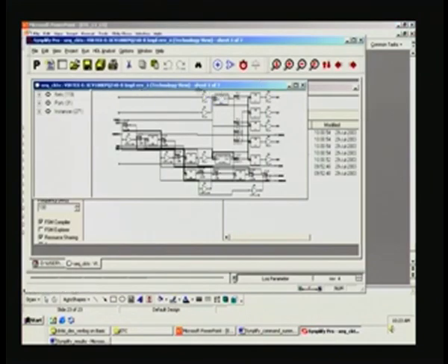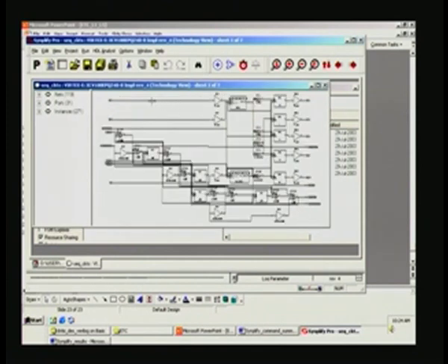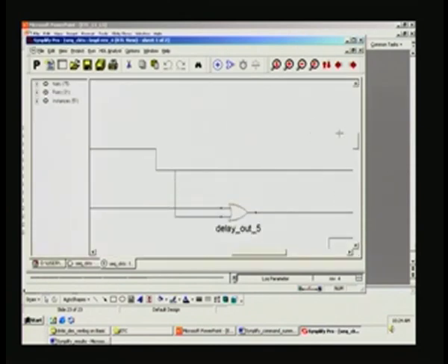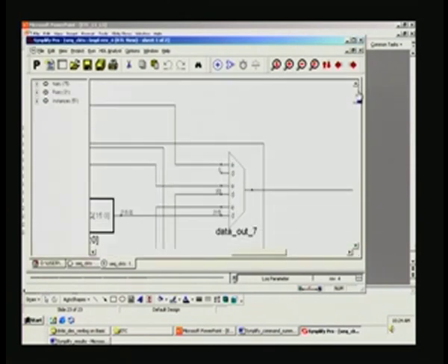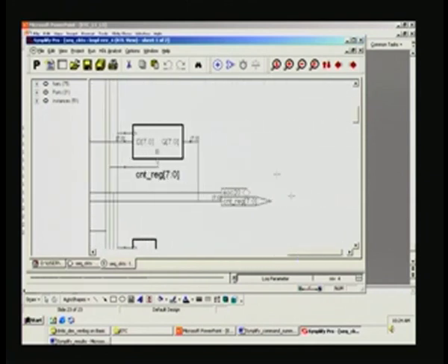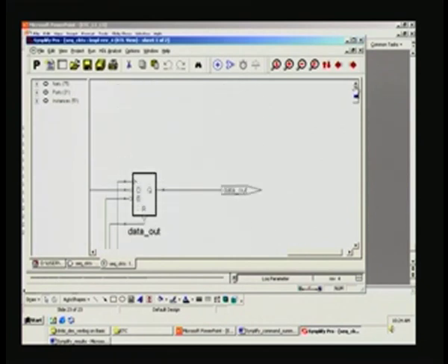It runs into 7 schematics, and as I mentioned, to wade through the schematic is a very difficult process even after optimization, and at least you must do it for one of them, as I recommended earlier. And here what you can see is the technology view, whereas in the RTL view, let us see how many sheets, it is only 2 sheets. So for the sequential circuits, if I blow it up, this is what you get here. Some counters are there, so you can see all that. You can just look at the outputs and then find out.